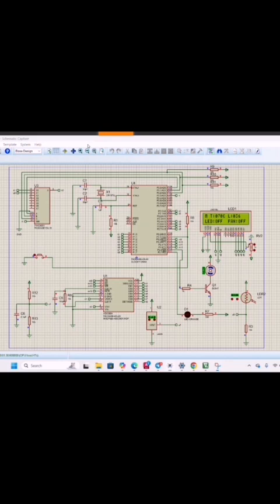One challenge I faced was controlling two analog sensors with one ADC, but I solved it by using a 74HC4051 multiplexer. I also had to carefully adjust the transistor circuit to make sure the LED was not always on.